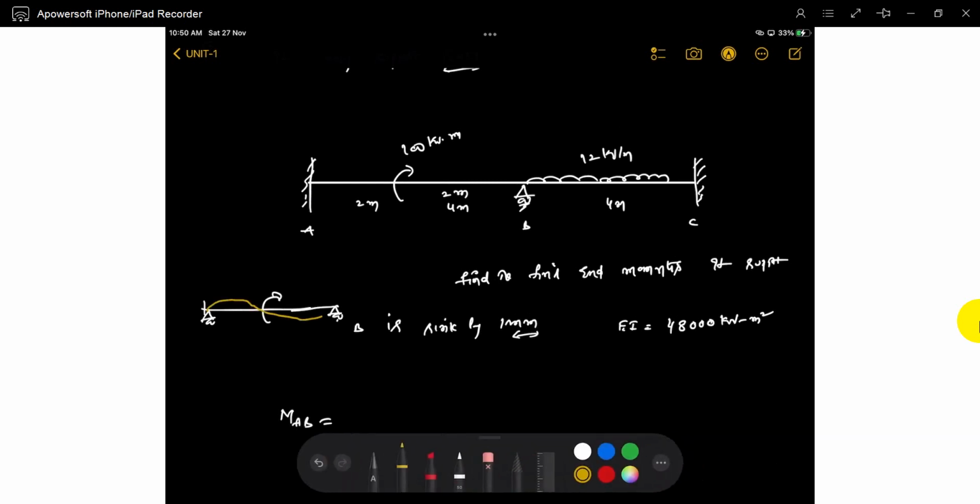It will rotate like this. So the moment is generated here. If those are hinge joints, it will rotate like this. If we want to fix those, we need to generate an opposite moment. Otherwise, if it is a fixed end, the moment is generated in this direction. What is that value? If it is m, it is m by 4.